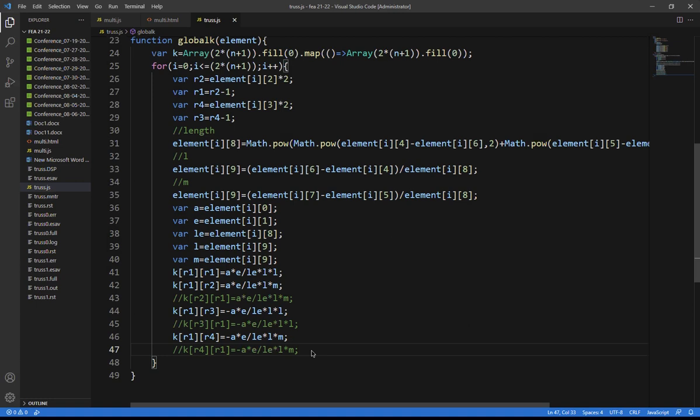And next time we will see how we can apply the, see, once you prepare the global stiffness matrix, it's hardly anything else. The next program is to apply the Gauss elimination method, which already you have written, because it is KQ equal to F. Now you can pass on this K, Q and F, it will solve it. Okay, so the challenge is to prepare a global stiffness matrix. That's it. Once you are able to prepare it, K, Q, F, you pass on to the Gauss elimination method and it will solve it for you. Okay, so if you have understood this up to this, you can type it, and next time we will continue.